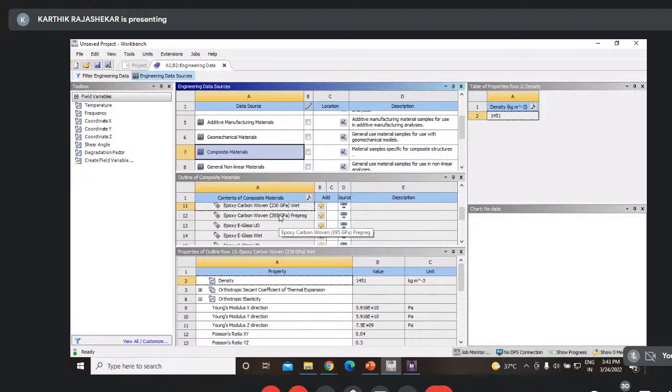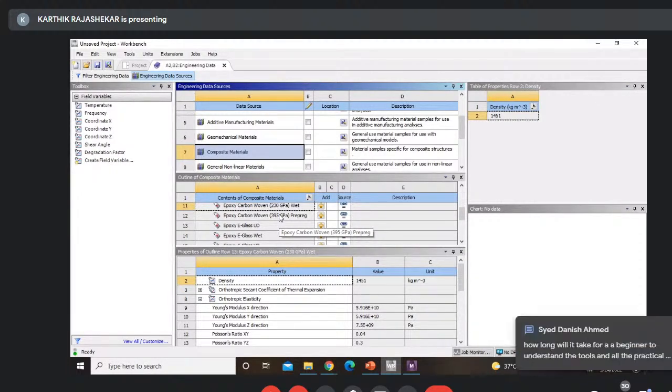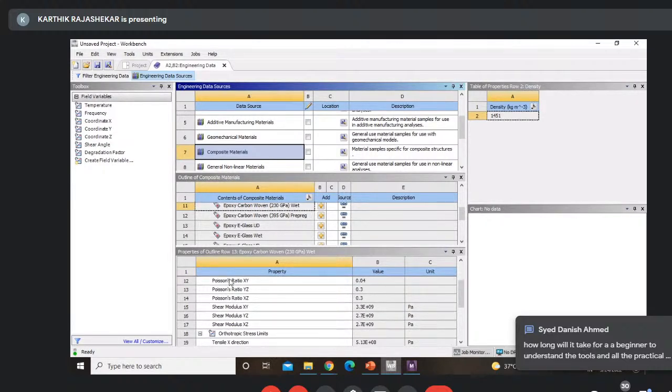go for tensile testing. So create composite samples according to the ASTM standards, do the tensile testing. From the tensile testing, you can generate the results. You would be able to apply those things, generate the Young's modulus, all those things, and the same thing can be incorporated into the software. So using this again, you can do it.